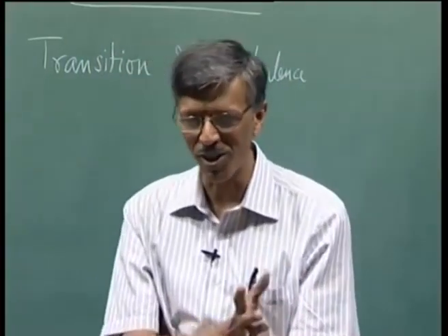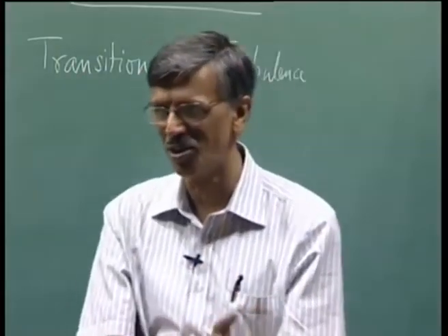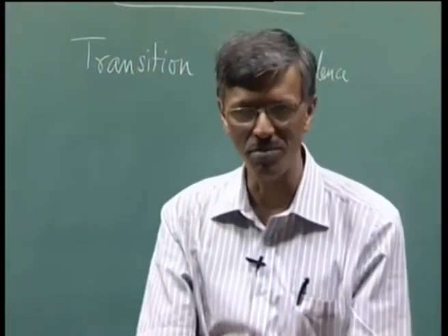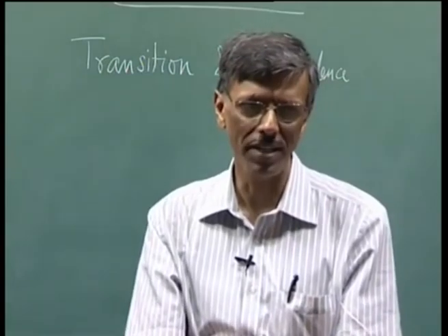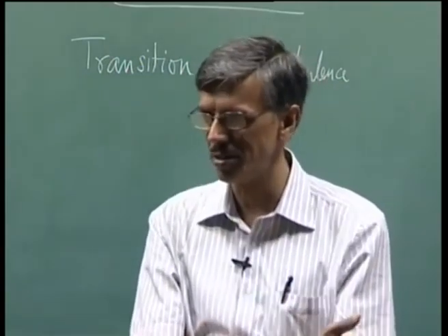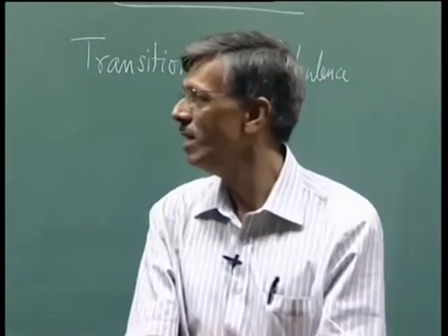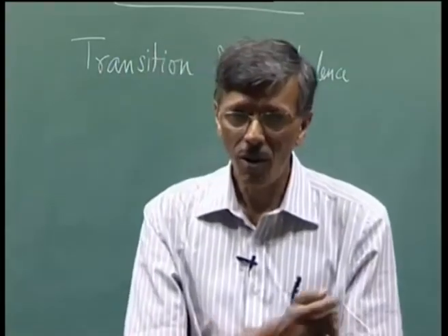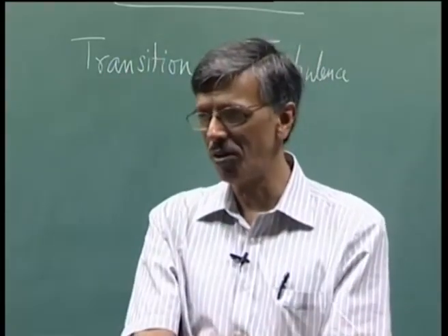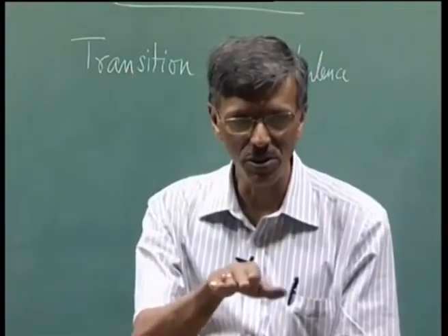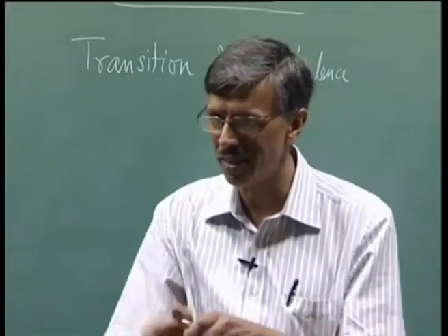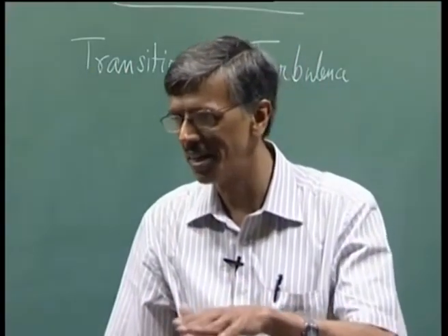What we are going to talk about is the reality, not the virtual one where people make tall claims. You really have to design a tunnel where background disturbances are brought down to 0, and only then you have to excite the flow deterministically, like I told you in the Schubauer-Skramstad experiment, where inside the boundary layer you started